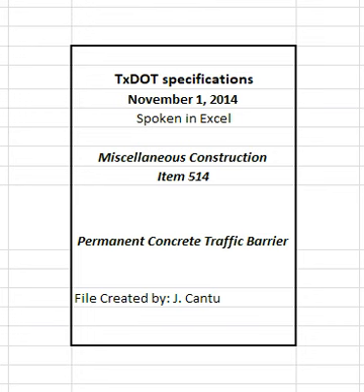3.2.2 Slip-formed barrier. Ensure slip-formed barriers are within a vertical and horizontal alignment tolerance of plus or minus 1/4 inches in 10 feet. Construct barrier with a smooth and uniform appearance. Remove and replace unsatisfactory barrier at the contractor's expense. Consolidate concrete so it is free of honeycomb. Provide concrete with a consistency that will maintain the shape of the barrier without support. Minimize starting and stopping of the slip form operation by ensuring a continuous supply of concrete.